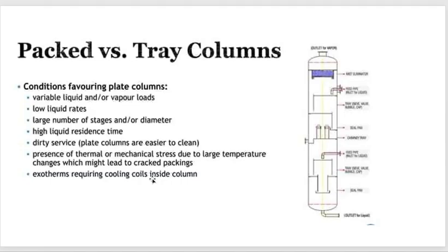There are some conditions favoring a tray column. Now you will choose, it's favored to choose the tray tower for variable liquid and vapor load, more controlling through the trays, okay? Low liquid rate, because as we see in the bubble cap, with low liquid rate it will not weep. Why? Because we have good control by the bubble cap. So if you are working with low liquid rate, it is recommended to choose the tray tower.